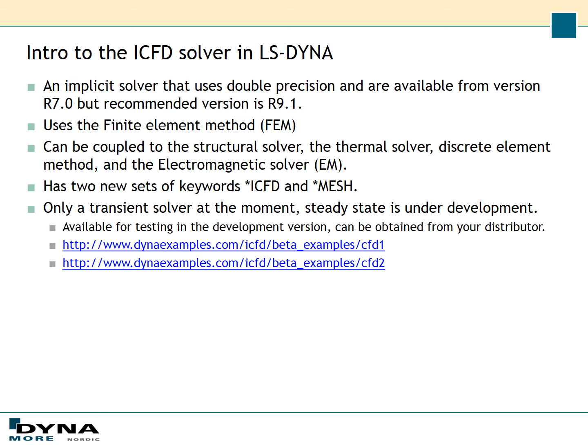And it has a new set of keywords, star ICFD and star mesh. And at the moment it's only a transient solver, but a steady state is under development. And if you are interested, two examples of the steady state solver is available at dynaexamples.com, but you have to contact your local distributor to get a development version of LS-DYNA.